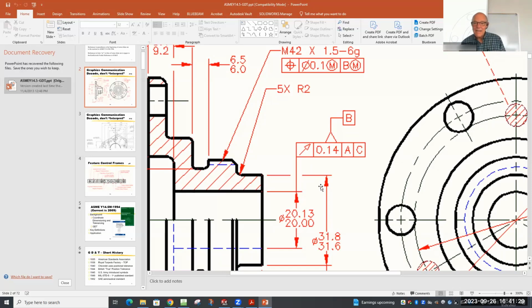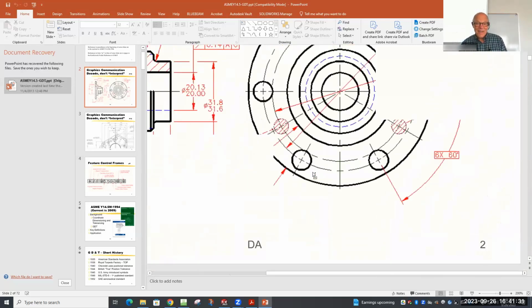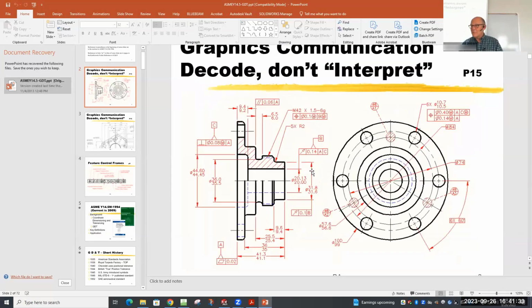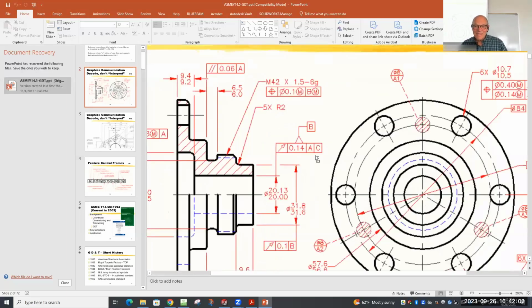On a mechanical part, if you have excessive runout and it turns really fast, it creates a huge amount of vibration. That vibration then causes failure. Say the rotors on your brakes on your car, which is this disc that goes between two brake pads, and those brake pads squeeze down on the rotor. If you've ever had a situation where, when you put your foot on the brake, it grabs, lets go, grabs, lets go, and they say, oh, we've got to turn your rotors, that means the rotors are now warped and they're experiencing runout. They go back and forth as they turn. So that's runout.